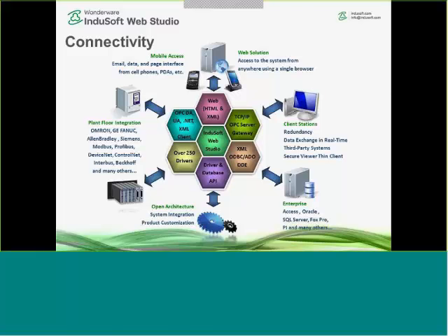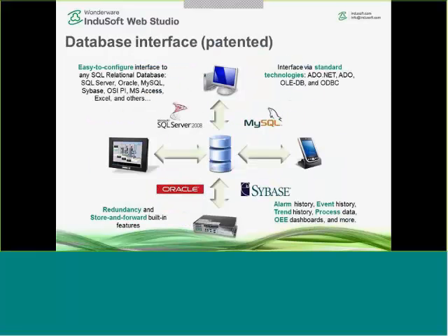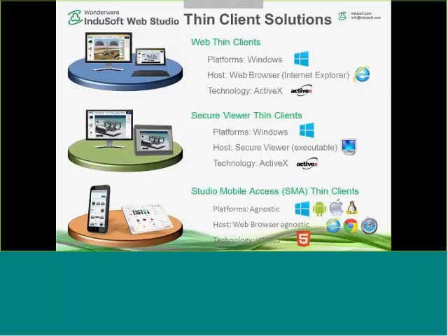So if a primary system goes down, all of the thin clients will remotely switch over to a secondary backup SCADA server, and then you have the database technology behind that, such that if you have a database connection go down, you also have the ability to configure your application to store data to a primary and a secondary database in a store and forward mode. So it's a very comprehensive, open platform that allows you to work with multiple databases and at the same time ensure your data integrity. We already talked about that, so I'll skip through that.